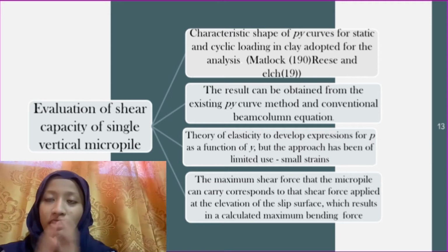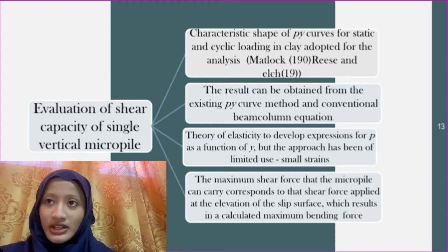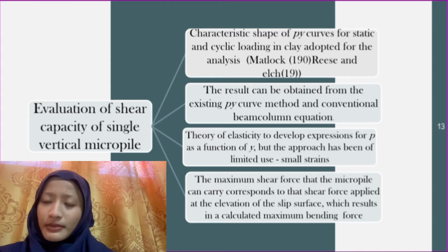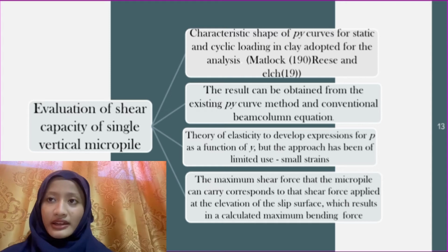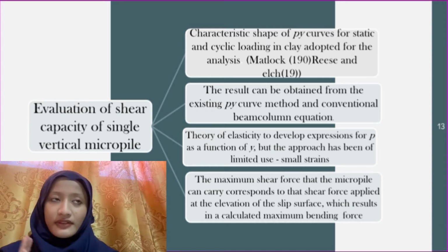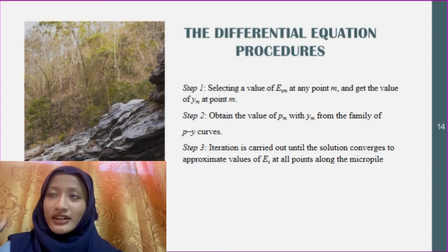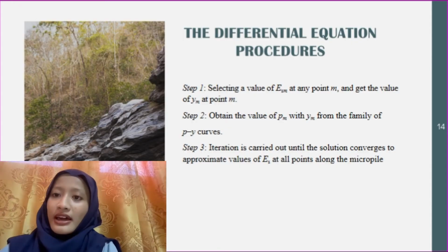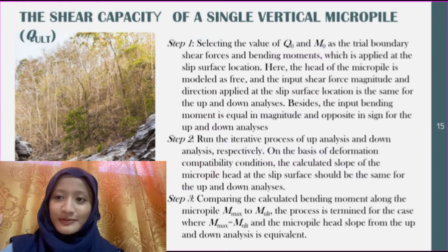For the theory of elasticity, to develop an expression for p as a function of y, the approach has limited use because of the small strength of clay. Lastly, the maximum shear force that the micropile can carry corresponds to the shear force applied at the elevation of the slip surface, which results in the maximum bending moment. This is the differential equation procedure, and this is the shear capacity of a single vertical micropile.